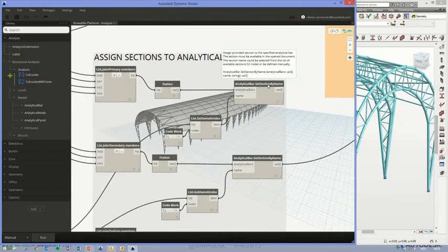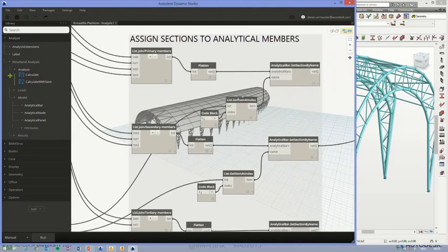It's possible. So an alternative on this workflow could be that you start your model in Revit, you open Dynamo from in there, you select the surface in Revit, and then you generate your system and connect it to Robot. That's possible. In this case, I decided not to do that, exported the mass geometry from Revit to an SAT file, and then bring in that SAT file in Dynamo to reuse those surfaces. Okay, so I assume that the geometry won't change anymore by the architect.